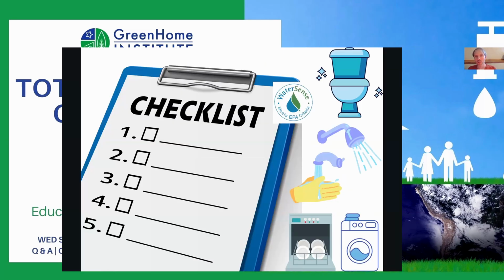Usually under the prescriptive checklist, you're looking at toilet gallons per flush and then gallons per minute of bathroom aerators and shower heads, and to have all three of them ideally be WaterSense certified within the prescriptive pathway. Then looking for Energy Star certified clothes washers and dishwashers to get your points there. Note that Energy Star dishwashers are only required in LEED as a potential item in the energy and atmosphere section, as opposed to the water section for prescriptive.